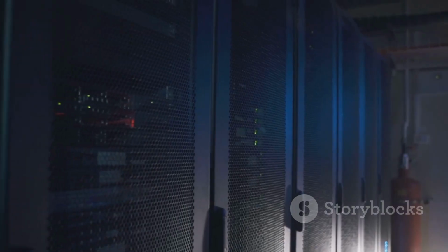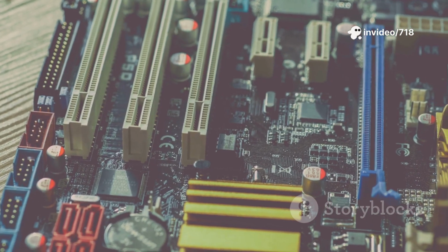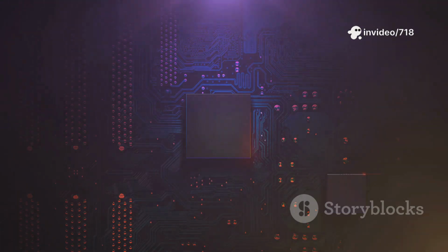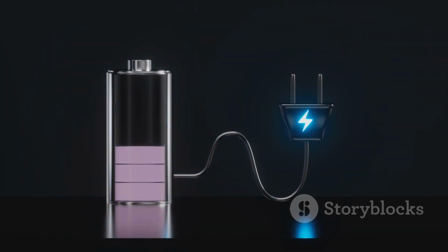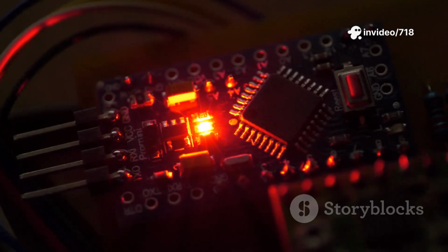The bit lines are the data carriers. These are long, vertical wires that run through the columns of the grid. Each bit line is shared by all the cells in its column. When a word line is activated and the transistors open, the stored charge from each cell's capacitor flows out onto its respective bit line. Now, the amount of charge is incredibly small.